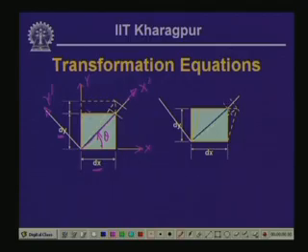and here in the y direction it is undergoing extension, where the extension from its original form is equal to epsilon y times dy. So, epsilon y dy is the extension of this element, and because of this stretching the diagonal which was originally of length ds is now getting changed, and the extension is given by this particular part of the diagonal.